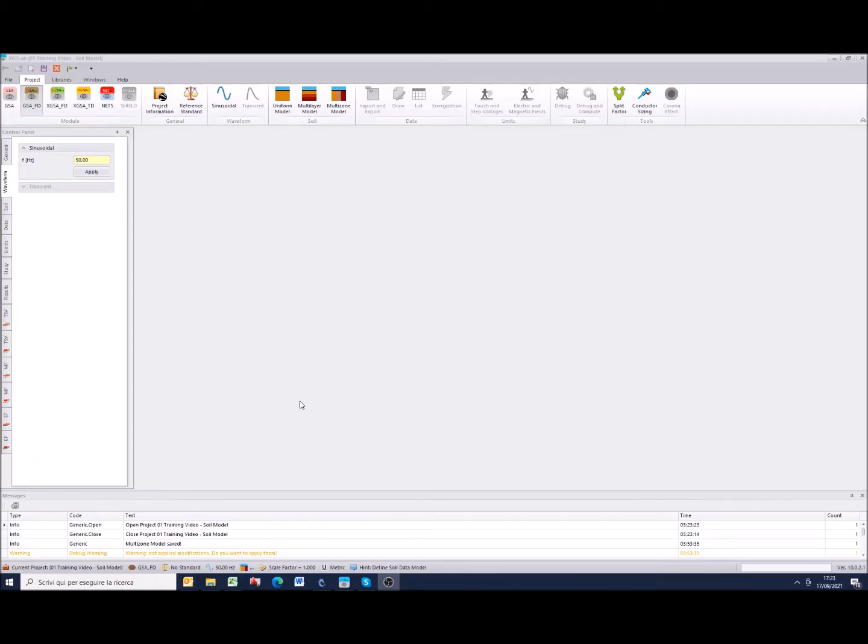In this video, we are going to see how to handle a soil model in XGSLab software. So we have just set a 50 Hz frequency, and we have to notice that we have three different models available: uniform, multi-layer, and multi-zone.